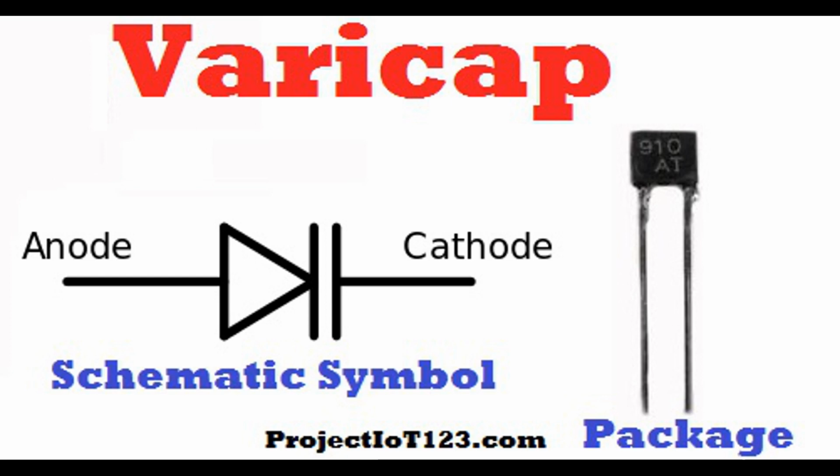Voltage-tuned oscillators. These VCOs use a varactor diode to vary the capacitance and, consequently, the oscillation frequency with an applied voltage. 7. Design considerations. Designing VCOs involves considerations such as stability, phase noise, tuning range, power consumption, and output waveform purity. Voltage-controlled oscillators are versatile and essential components in various electronic systems. Their ability to generate frequency-tunable signals makes them valuable for applications ranging from wireless communication to test and measurement equipment.